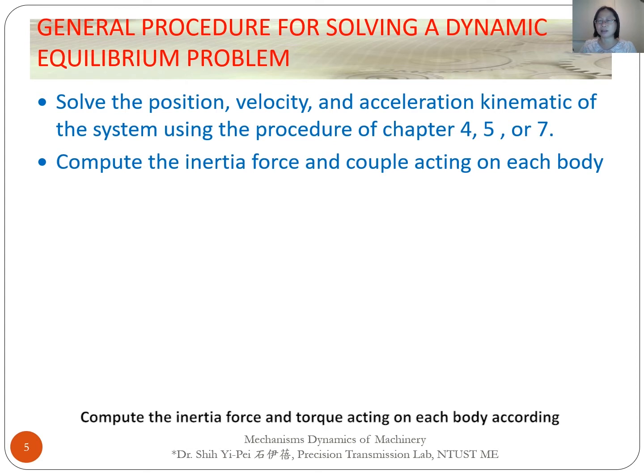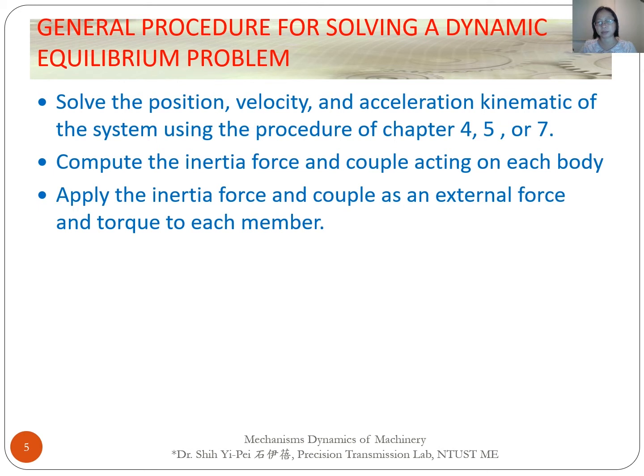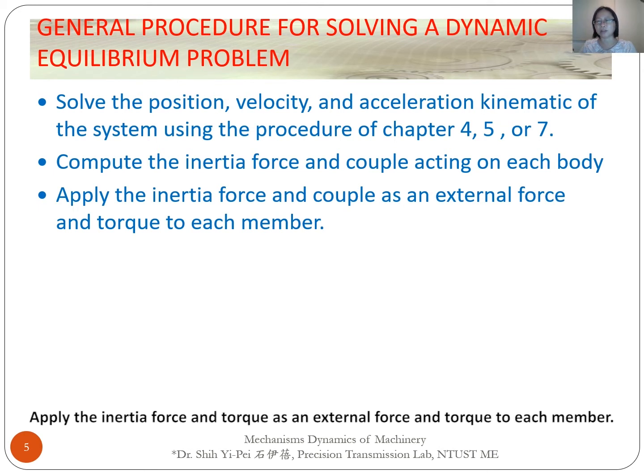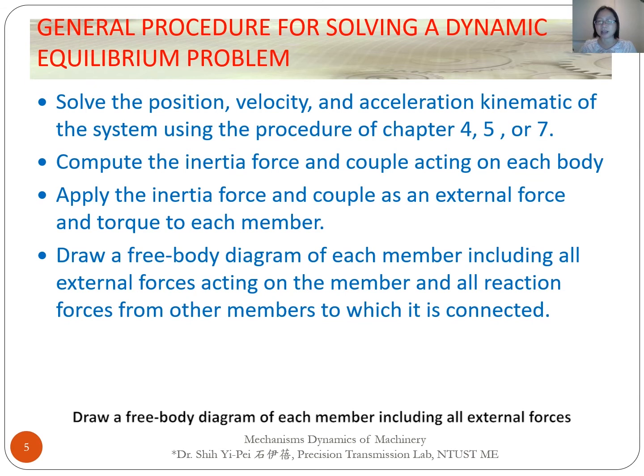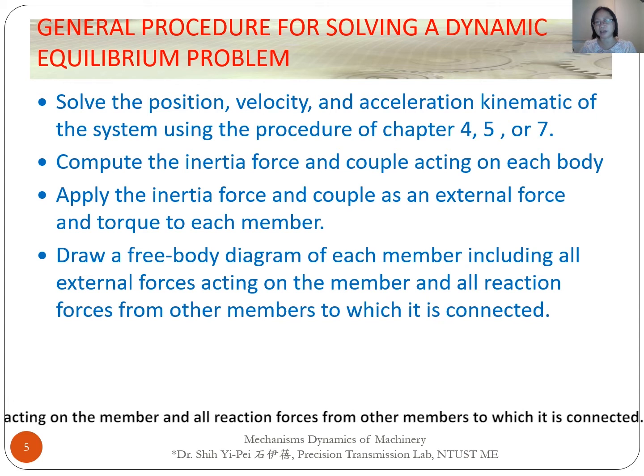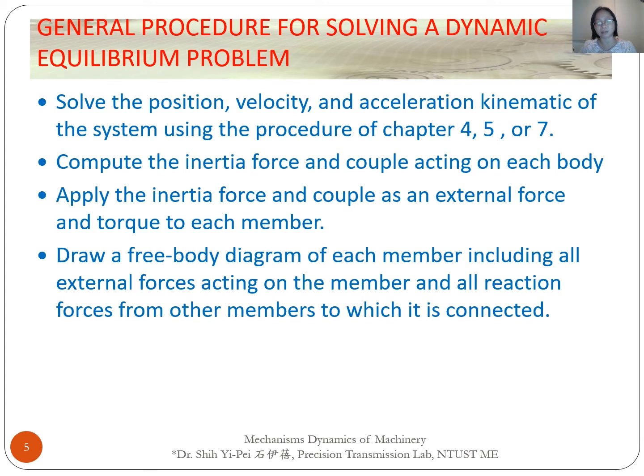Compute the inertial force and the torque acting on each body according to D'Alembert's principle. Apply the inertial force and the torque as an external force and torque to each member. Draw a free body diagram of each member, including all external forces acting on the member and all reaction forces from other members to which it is connected.